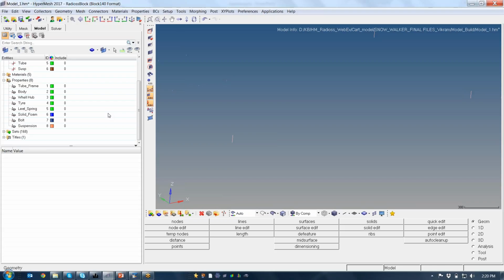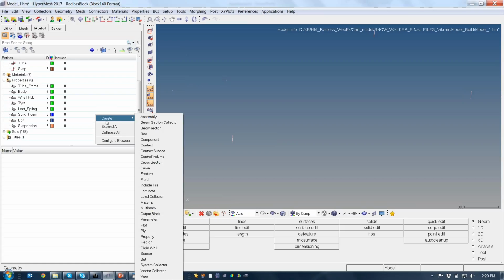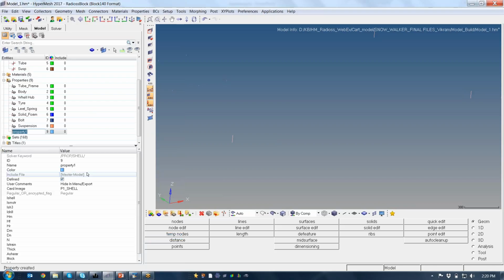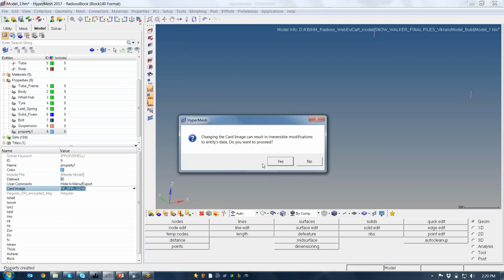You can use them. Otherwise, if you want to model simple joints like revolute and cylindrical, you can live with one particular spring itself, which is our type 8 spring, the spring general.